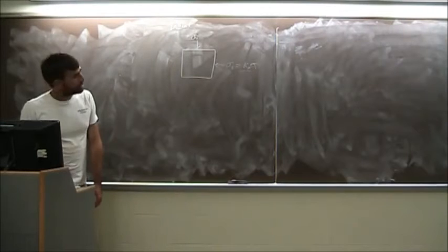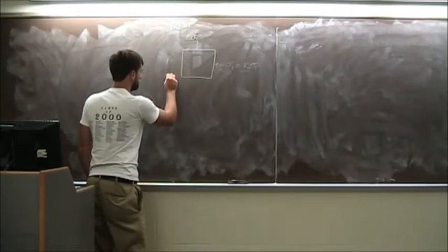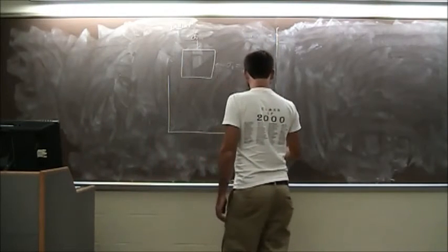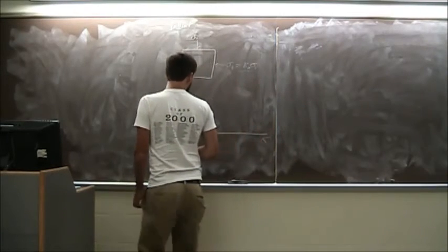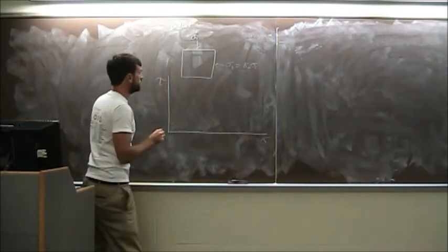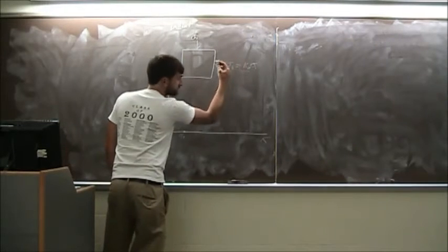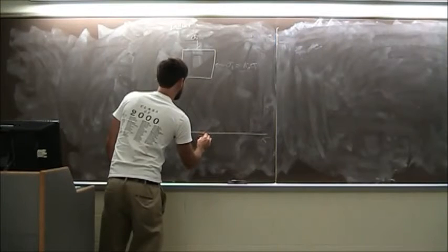Okay. So if you want to plot this on a Mohr diagram, you have tau and sigma, and you have sigma 3 here, because that K value is less than 1, and you're going to have sigma 1 over here somewhere.